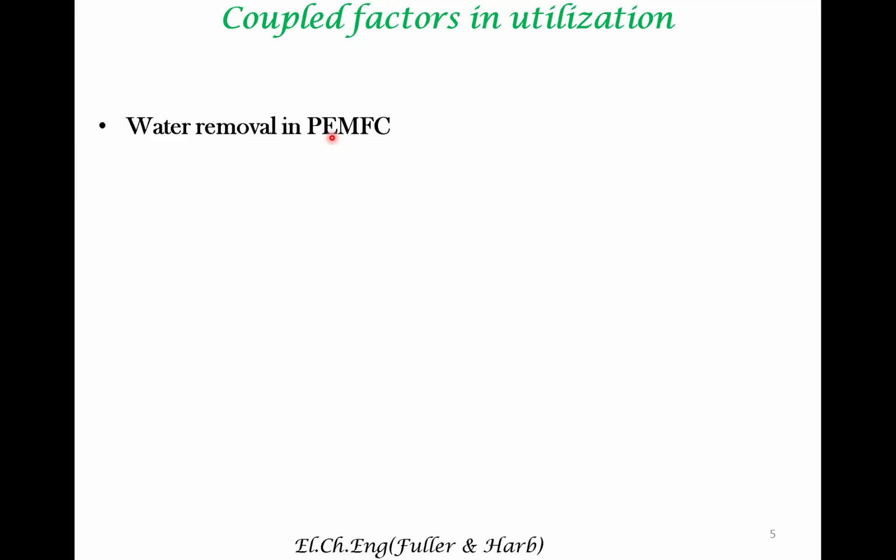Too little removal of water or too much removal of water, both these extremes are not desirable. So there should be an optimal trade-off in the removal of water to maintain a balance in terms of proton conductivity and in terms of mass transfer resistance for oxygen to reach the electrode. So a lot of engineering goes into all these things.